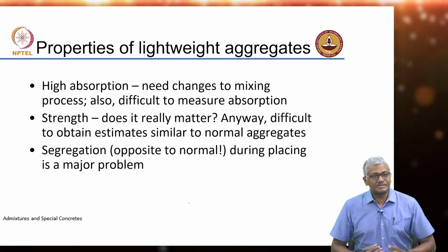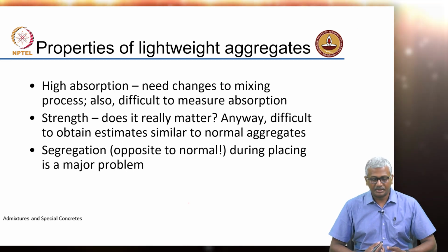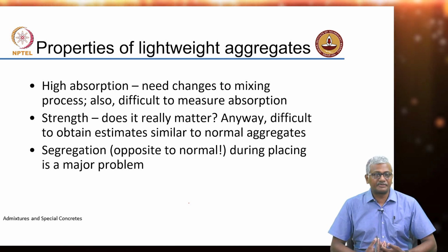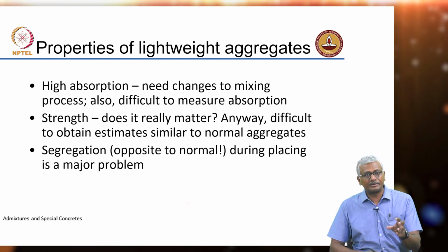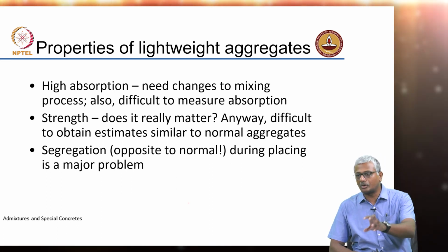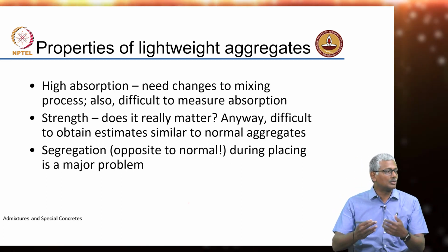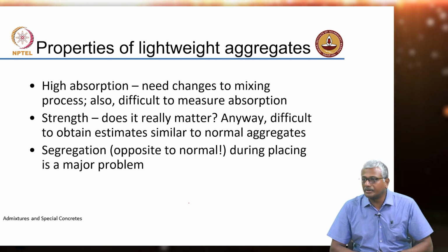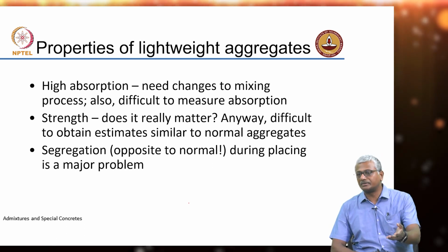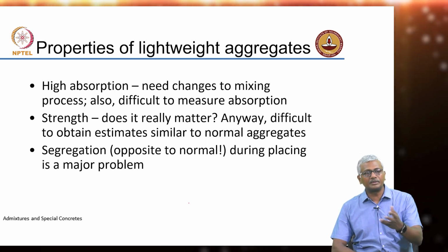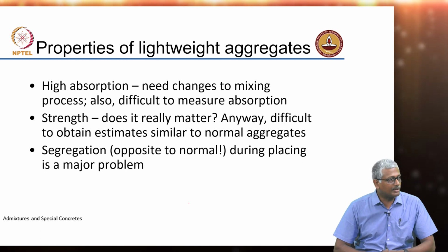Now, lightweight aggregates have high porosity, so obviously they will have very high water absorption. You need to change the mixing process, because if you put the lightweight aggregate in a dry fashion inside the concrete mix, it is going to absorb all your mixed water, and you really do not know how to then control your workability. So, generally when lightweight aggregates are used, there is a pre-soaking that needs to be done. You pre-soak them and make them saturated surface dry before you utilize them in concrete.